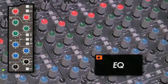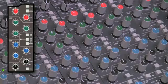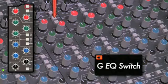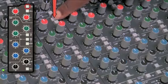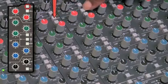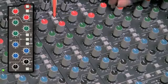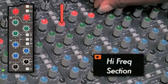Here we have a 4-band parametric EQ, based on SSL's classic black knob EQ, which was developed for the SSL 4000E console. At the very top of the EQ section, we have the G EQ switch. With this desk, you have the option of 2 different types of EQ curves, the E-series curves or the G-series curves. The E-series curves have more of an aggressive character, while the G-series is a bit more of a smooth sound.